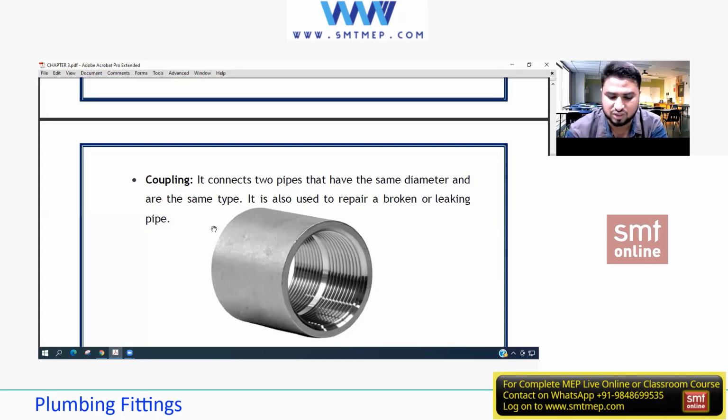So that is CPVC or PVC or any kind of plastic category of pipe. So what happens over here? We have some kind of adhesive, like a cement solvent or a glue. First of all, the internal surface of the pipe, when it's been cut, needs to be filed and cleaned up. The fitting needs to be cleaned with a soft cloth just to remove the dirt and impurities. Then we apply this kind of glue, and we do have some cement solvent, some kind of solution, and they just apply it and fix it. So this is a permanent joint, not a temporary one.